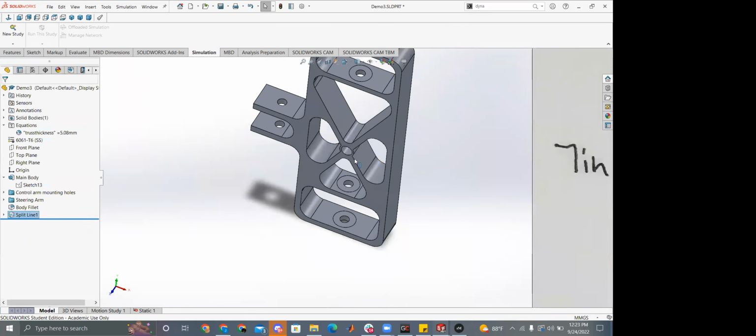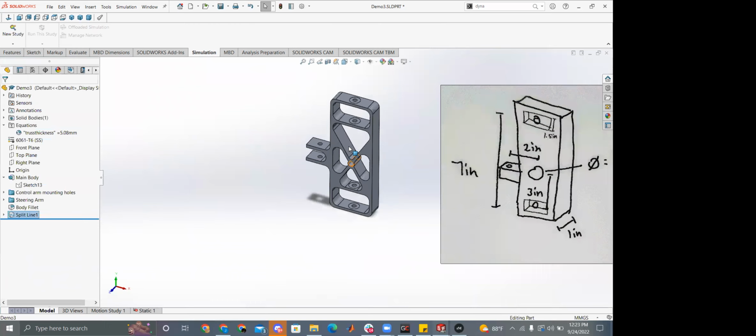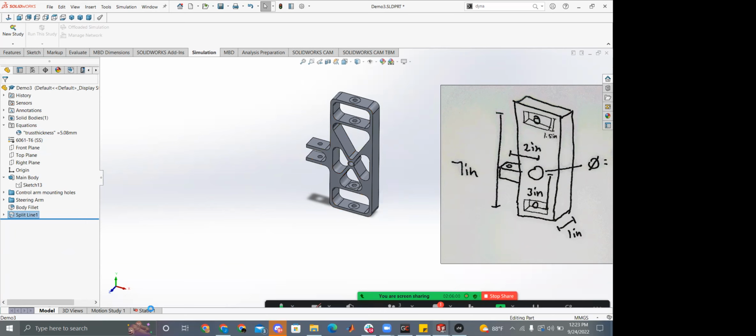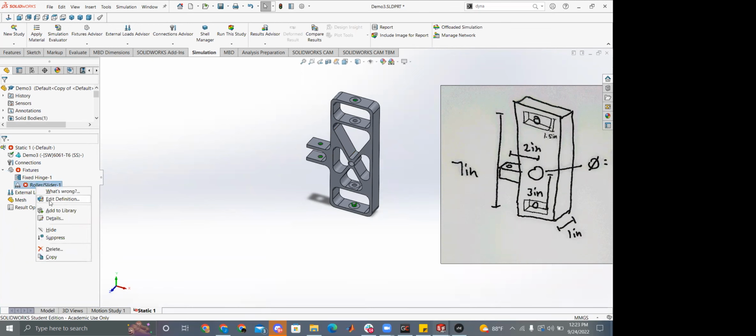Because if we have a force going up on this upright, then the normal reaction force, which is the force from the contact between the washer and the upright, is what's going to prevent it from moving. It's going to be on the top and on the bottom. If put on the bottom, that would be like we glued it there and it's holding it from pulling up. If we put it on the top, it's like something that's in the way of it moving up. So we want to put the split lines on the top. My mistake. It's probably going to error out on me.